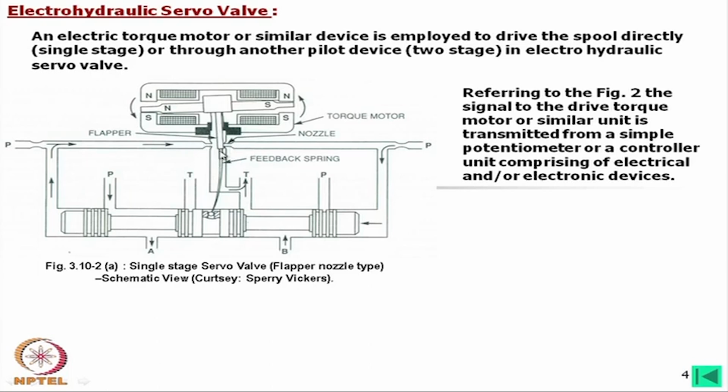Due to this differential pressure, it will always try to keep a particular position depending on how much torque we have applied here. Okay. And then this is the inside feedback, you can say the feedback spring. This is called the feedback spring, and this is being controlled not only by this spring, but also by this flow here.